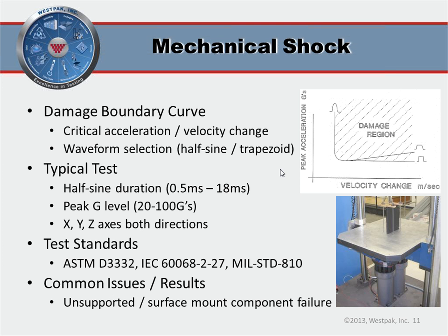Now there's an excellent question, and the answer is yes and no. You are absolutely correct that the best possible information comes from constraining, or what we call fixturing, the product in the same configuration in which it will receive the shock pulse, either during its lifetime or during its shipment or any portion thereof. So as a practical matter, what we'll do is an estimate of the fragility of the product early on in the product's development cycle using relatively simple fixturing. As the product progresses in its development, in its shape, and its configuration, we want to make darn sure that the testing also reaches the same level of maturity.